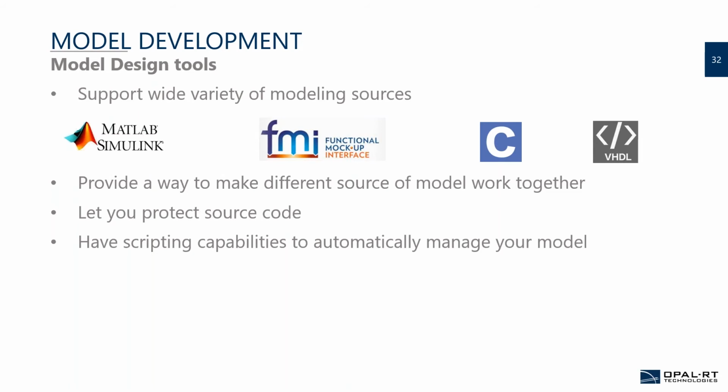Maybe you can have a routine so that when you have a new C code that represents one part of your system, instead of doing all the changes, compiling the library, porting the library to the environment, and making the link, which are usually always the same, you can script them with an API and control the tools through the API to compile, to load, and do everything. That saves you a lot of time in the long run.